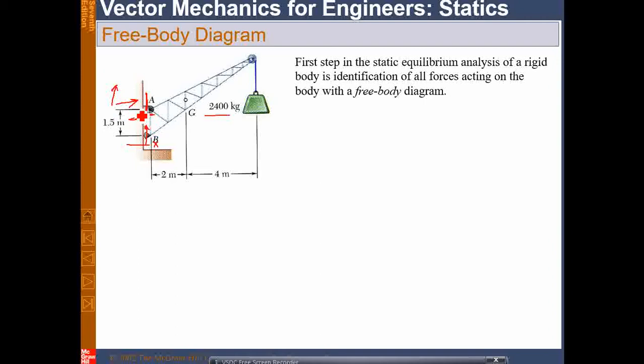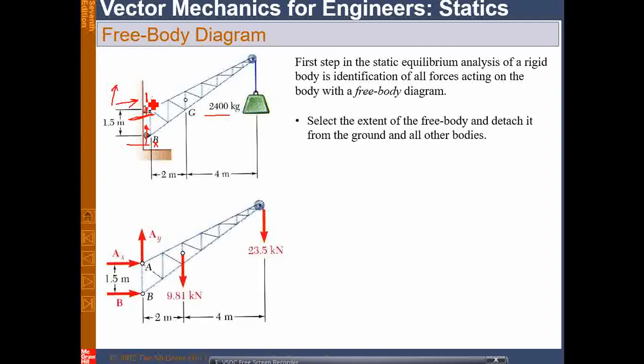So there will be one reaction coming at this, and similarly the y-axis is also constrained, so there will be one reaction coming to it, like this. This reaction came since the movement along x is fixed, and this reaction came along y because the movement along y is also fixed, because point A is fully constrained. Similarly, point B is allowed to move in the vertical direction, so there is no vertical component because the movement is allowed. However, the horizontal movement is not allowed, so the reaction at B exists.